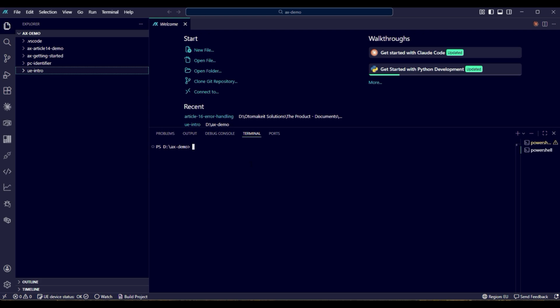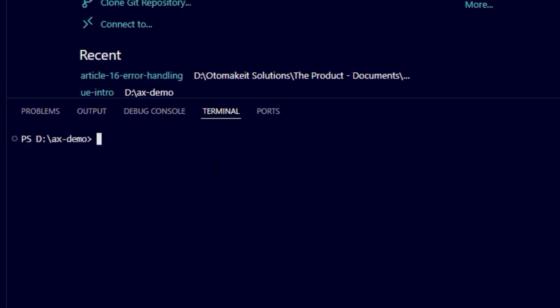So let's create a project. We're gonna use command apax create. Then the type of the project is HWC app, because this is a hardware including project. It's not just a code project for creating function blocks for TIA portal. That's a standalone project including hardware configuration. So let's call the project AXtankDemoProject.